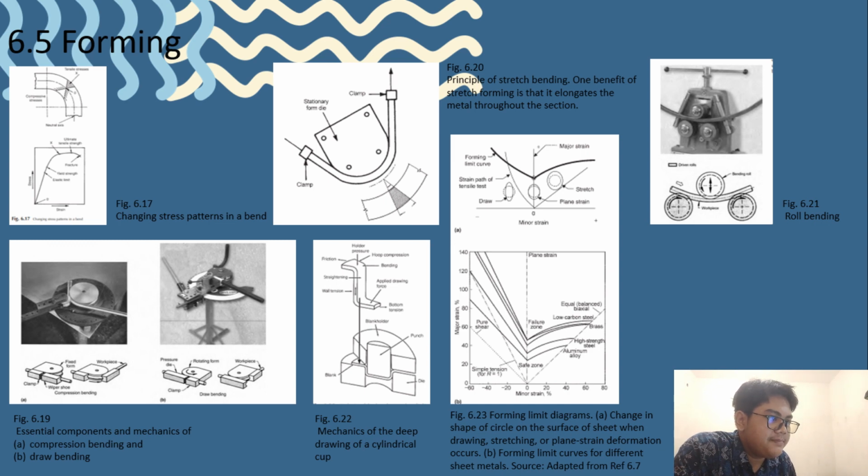The sketch in figure 6.17 depicts the change in tensile and compressive stresses in the bend zone. The metal nearest the neutral axis has been stressed to values below the elastic limit. This metal creates a narrow elastic band on both sides of the neutral axis, as shown in figure 6.18.